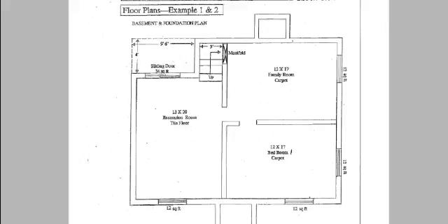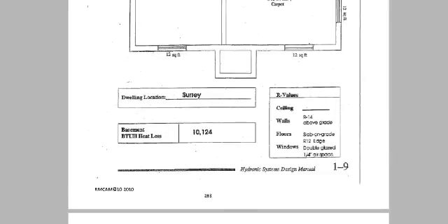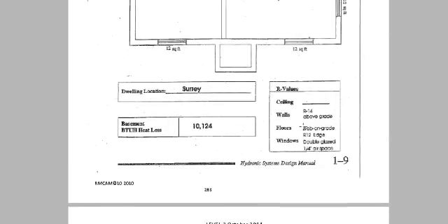There is a slab on grade floor and it is detailed as R12 edge, so that would be insulated around the edge. And we'll be looking up those items on our heat loss factors sheet, which comes with this, as well as our double glazed windows with a 1/4 inch airspace. All of this information, of course, you can find at the bottom of this page, labeled 1-9.